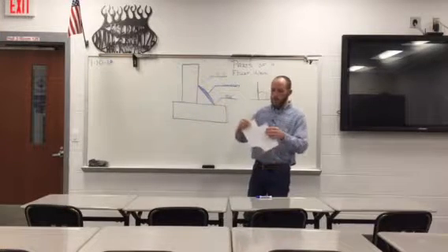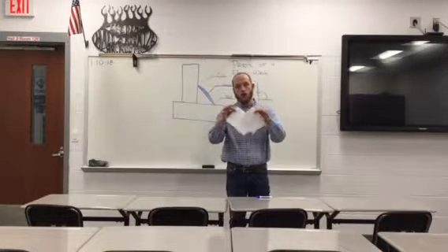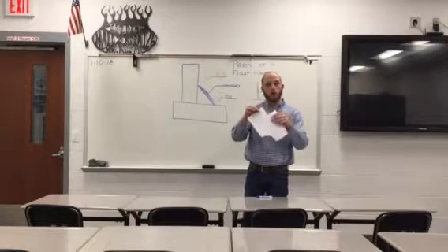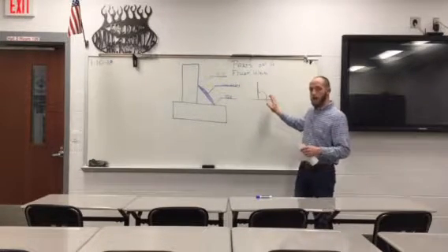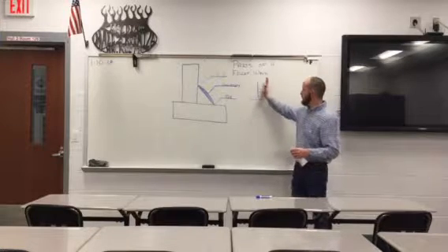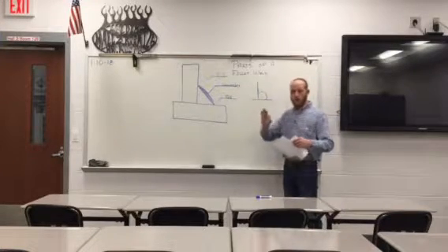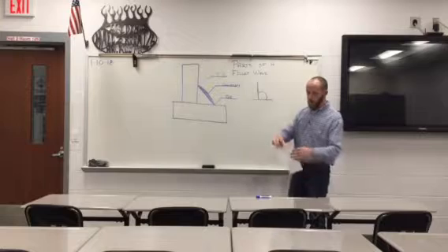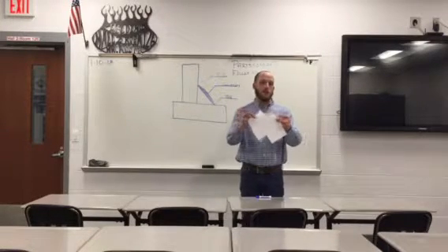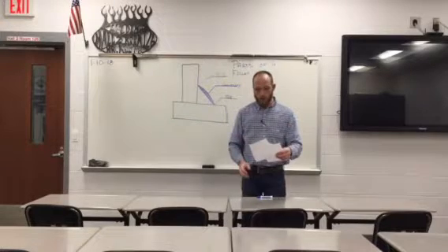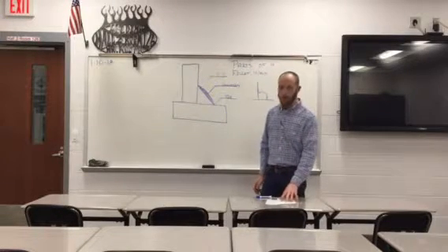If I apply very little pressure, it's going to rip that sharp corner. Same thing with this weld. These sharp corners are going to tear every time. If this was to try to bend back, it's going to rip every time. Now, if we had a good, nice, smooth transition, we have all kinds of strength in our weld. Same way with this piece of paper.